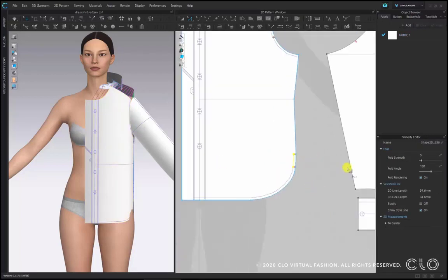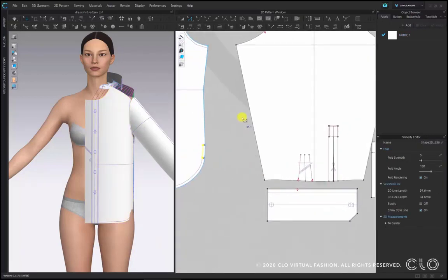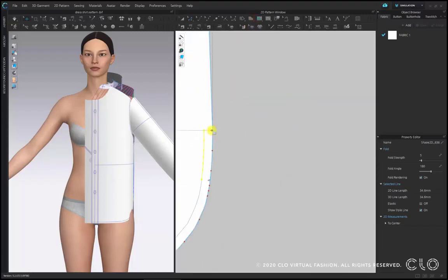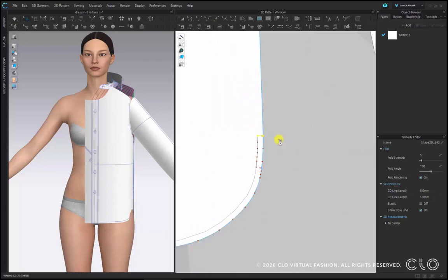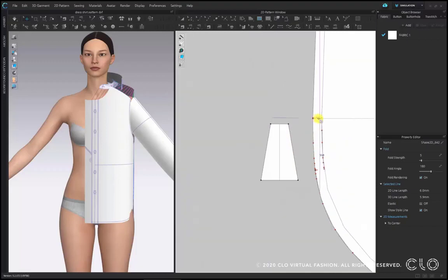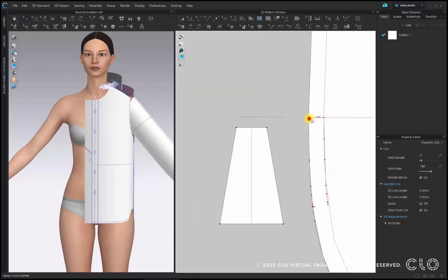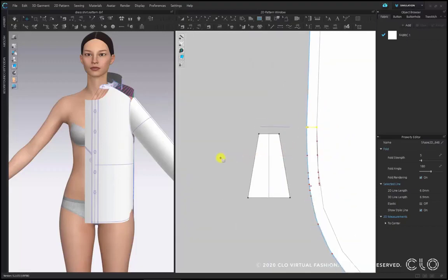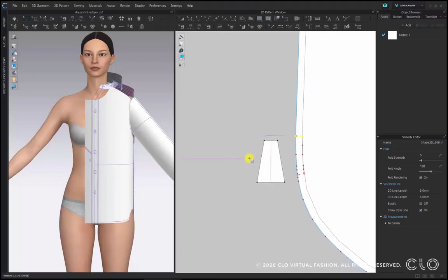The upper part of the gusset will also be sewn. So this time I select the internal polygon line tool. I click to start the straight line based on the point at the top, and then double click to finish. The same goes for the other side. And then I can start sewing the gusset on.